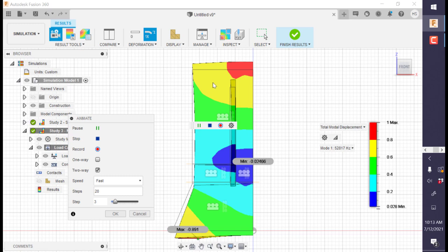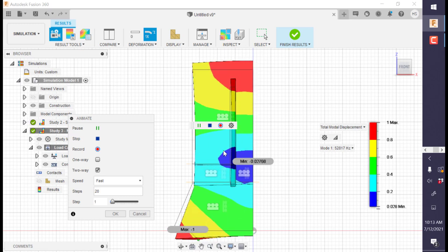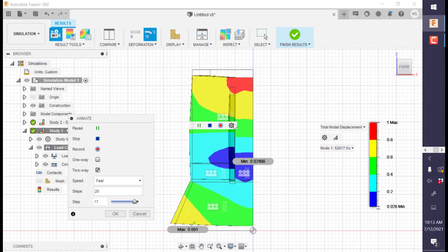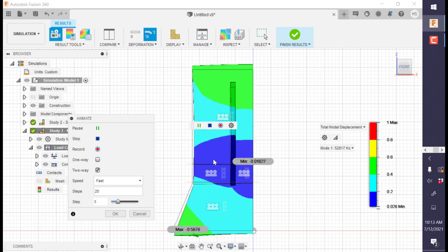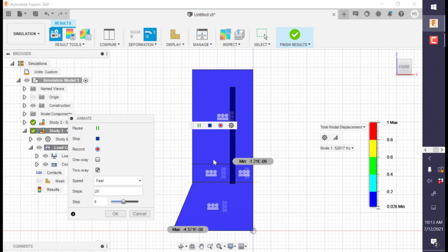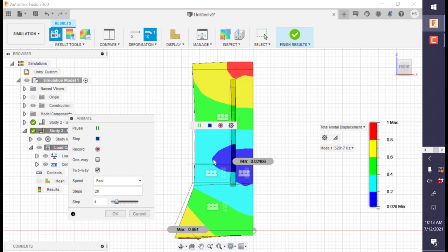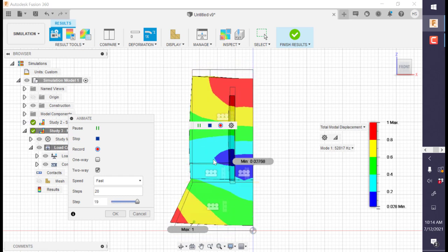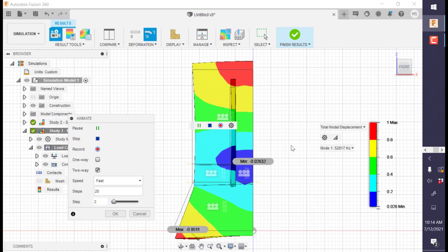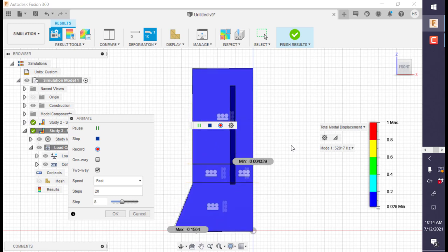Now, if you put your piezo anywhere along this transducer, you would still be able to provide excitation, but the excitation would be weaker. So you would need to use a larger voltage, which has its own limitations. You could even invert these colors and say that blue is high stress and red is low stress, because the displacement and stress relationships for a longitudinal transducer will in general be opposite.